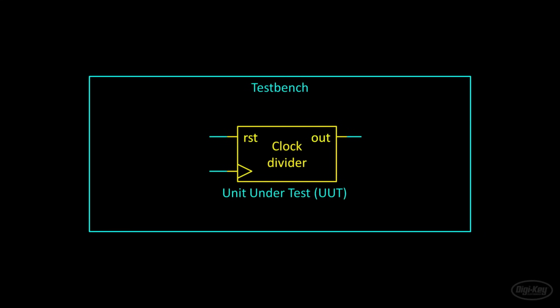In the previous episode, we used the top-level design to connect multiple modules together and connect the input and output signals to our physical pins. We don't have physical pins in a test bench as it's all simulated. So we use the test bench logic to drive the input signals. We can add glue logic if we want, but we mostly care about toggling the input pins on the test module so we can measure the output waveform to see if it matches our expectations.